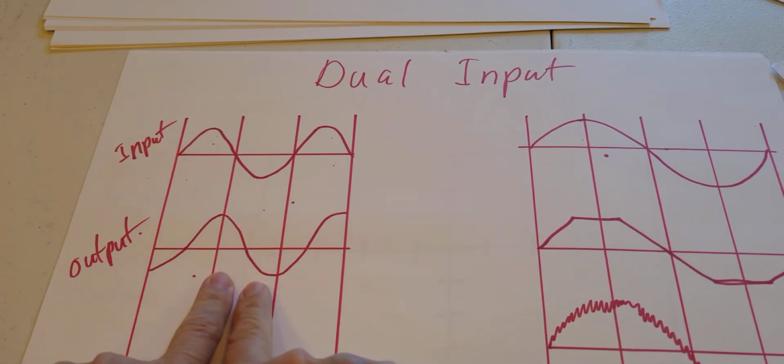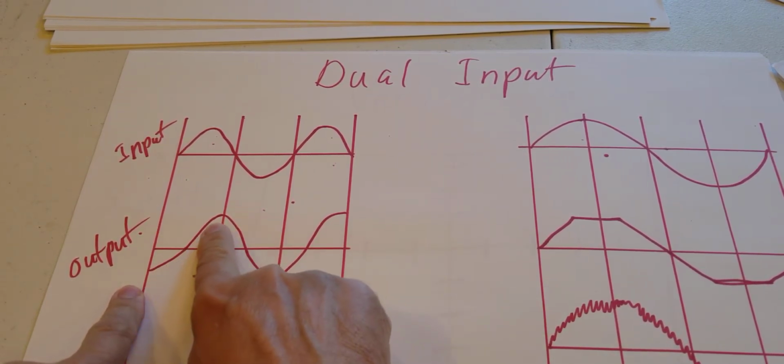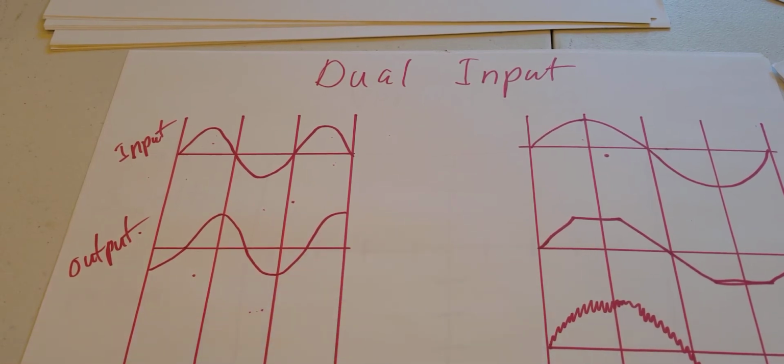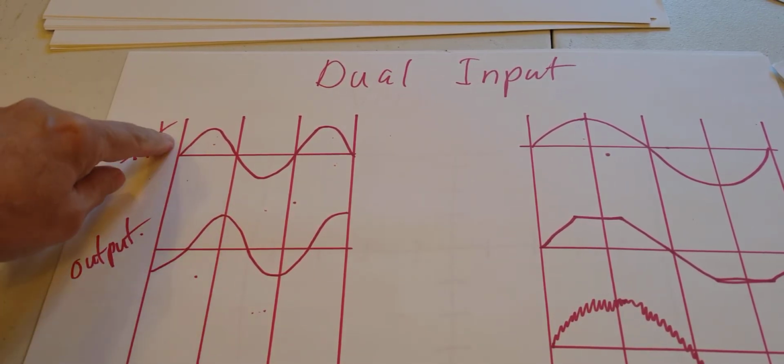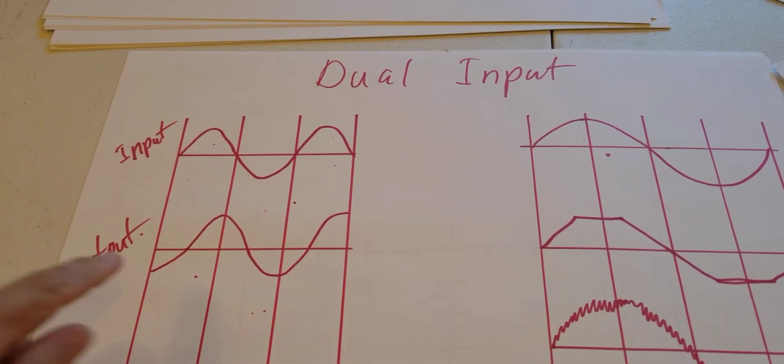output looks like this. You can see this is 90 degrees phase shifted. That might be something that's very undesirable in some circumstances, and in other circumstances it could be not even important. In others, it could be very desirable. In engineering, we actually make circuits called a differentiator or an integrator that would result in this kind of behavior. That was the input, that would be an integrator. That's the negative sign. This is a sine, a negative cosine, that's a sine. So that's a definite integral of this.